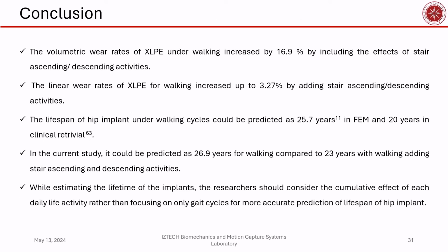We sum up this study. First of all, the volumetric wear rates of cross-linked polyethylene under walking increased by 16% by including the effect of stair ascending and descending activity. The linear wear rates of cross-linked polyethylene for walking increased up to 3.27% by adding stair ascending and descending activities.